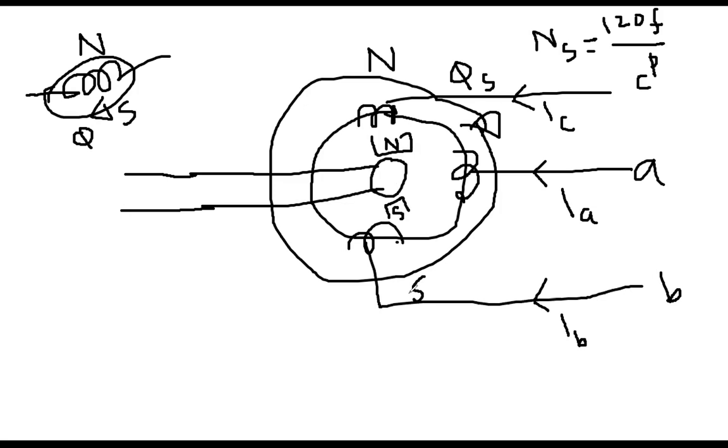You cannot see this internal pole, north pole, south pole. It is created because of the application of the three-phase voltage or three-phase current on the stator coils. Now, what will happen? Everybody look. Initially, the motor is not starting, meaning that because your physical north pole and south pole are placed on the rotor body, initially they are not moving because the shaft is static. But this one is moving.